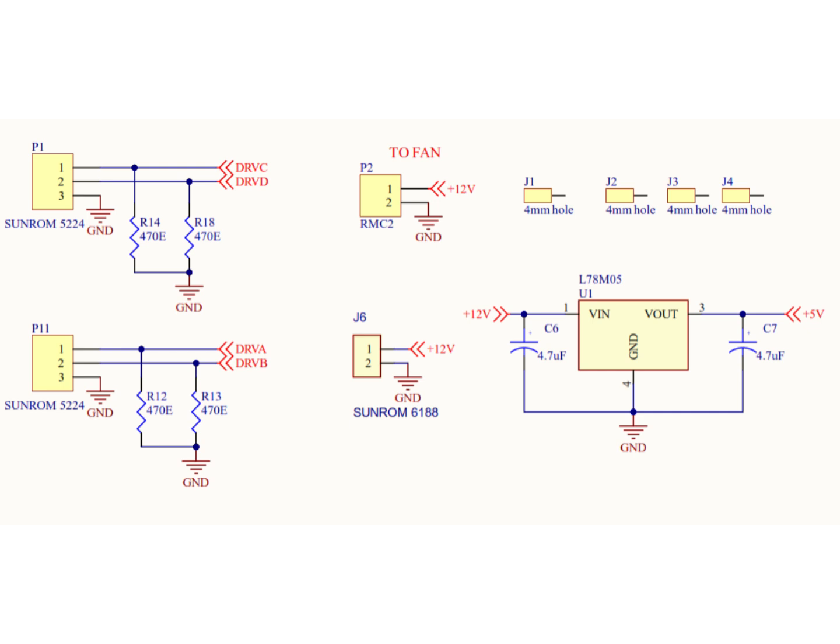Although the gate driver IC already includes an internal pull-down resistor of about 150 kiloohms, this value is relatively high. With long signal wires running from the STM32 to the gate driver board, these high-impedance inputs can easily pick up electromagnetic interference generated by the high dV/dt and high dI/dt power switching in the inverter. Under such conditions, false triggering of the gate driver can occur.